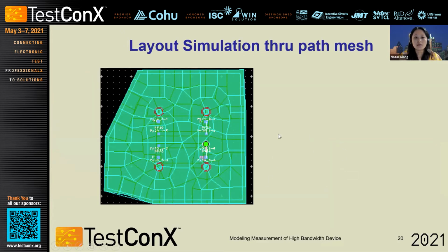So this is the slide that I'm showing you that we are doing study for the 2 millimeter traces. It's just the open traces that we also added in our board, the same board that we are using for the measurement of the test feature. You just connect it to the network analyzer, and then you can measure these particular traces, and then we do comparison of the measurement data versus the simulation data.